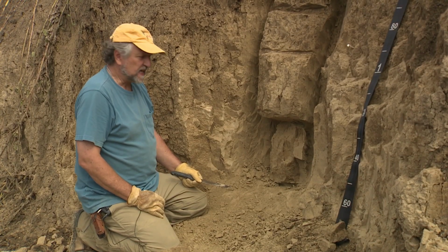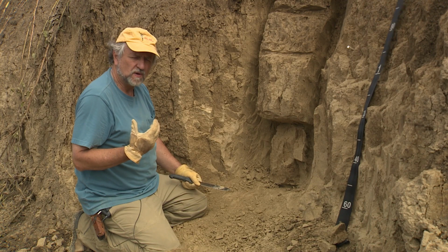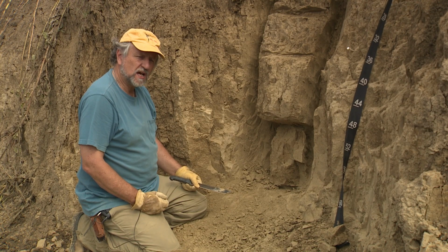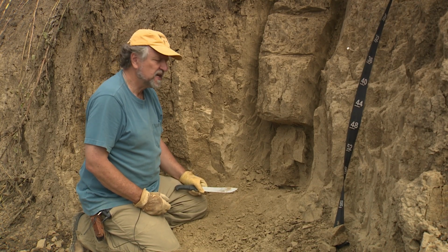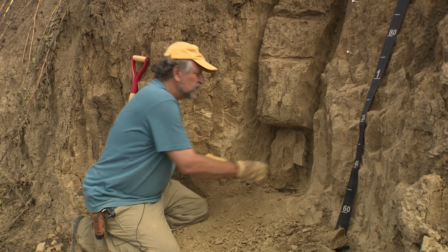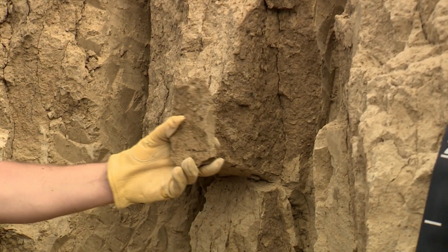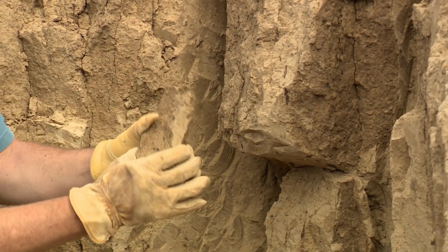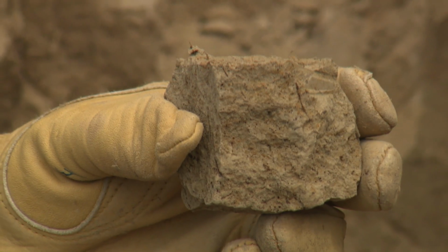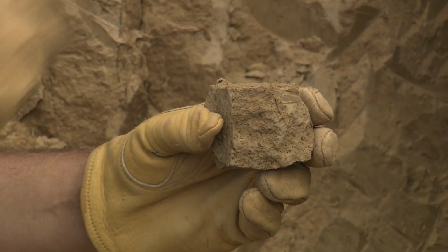For the 3 bulk density clods, the orientation of the clod in its natural setting when we extract it is not important. But if you're going to sample 2 clods for natural fabric or for thin section analysis, proper orientation does matter very much. So a clod has to be extracted in situ and its orientation maintained, so we know which end is up. Typically a pin or a nail or some other marker is inserted into the top of the clod so that when thin sections are prepared, they know which orientation is up.